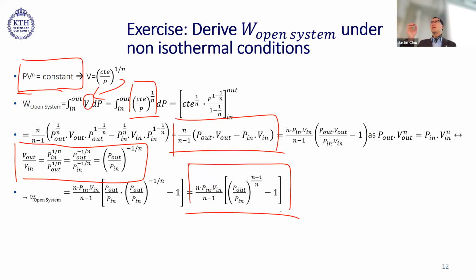Then you can calculate the power that is required to compress it. And then this n, very often we can assume it's an isentropic efficiency to get a theoretical value, or you can take the real n, which is the polytropic term that we can use, the ratio. So here, very often for air, we take 1.4. And then when we say it's polytropic, so considering some of the losses, then we can take 1.3.